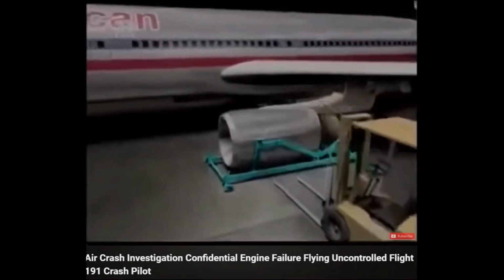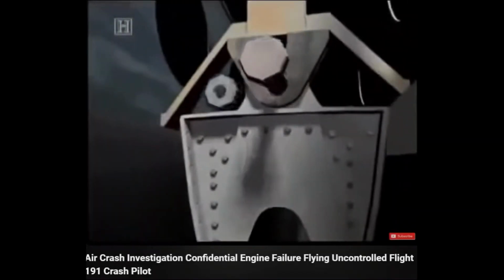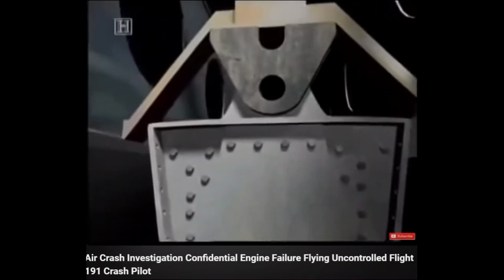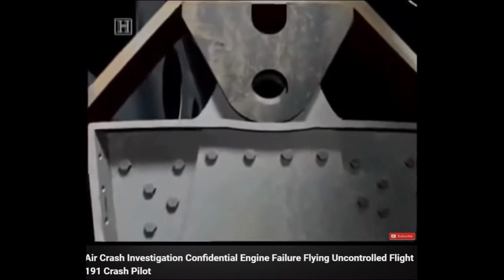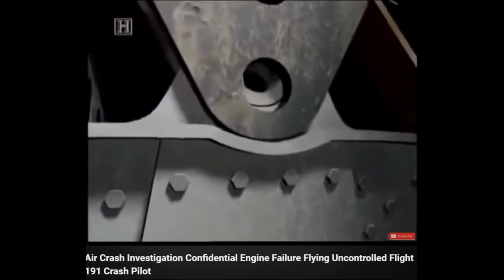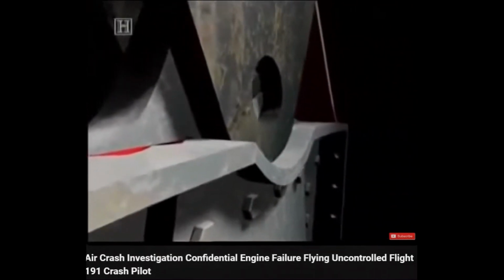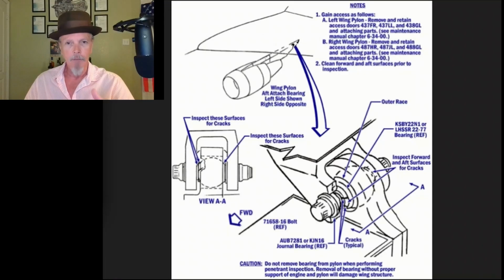McDonnell Douglas was aware of the procedure, but did not approve of its use. There was a deformation that was occurring right at the very top of this, where the mating clevis, where the engine and the pylon come together, as if the clevis had impacted that area and had produced the downward motion onto the flange that caused the crack. In order for the clevis to go down and make an impact, it had to have been disassembled at the time when that impact occurred. That clevis would not normally be at that position. So let's look at a diagram and a couple of photos.